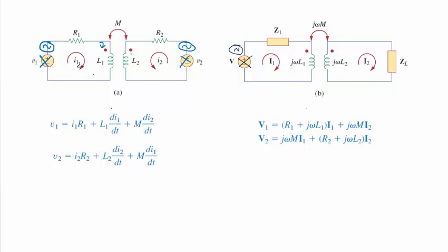So that means the induced voltage on the secondary side has this polarity, which is equivalent, if I'm writing a loop equation on loop 2, to, so plus hits first, plus hits first, plus hits minus. So that's equivalent to saying a little induced voltage is over here in this loop when I write the loop equation. So that M dI/dt is the size of it.